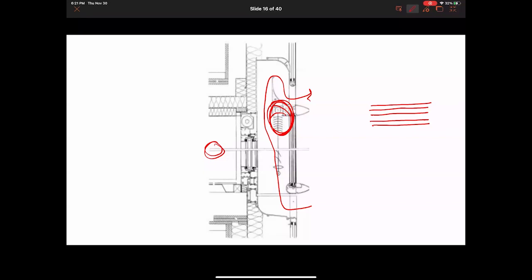Inside is only about 80% as effective. So if you have shades inside the building, it's only about 80% effective. Why? Go ahead and put it in the chat. Why would inside shades be not as effective as outside shades? Now, 80% is not bad.